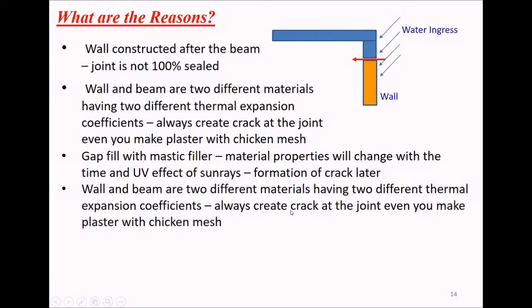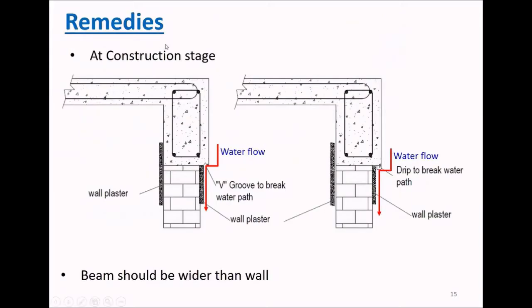So always this crack is there. We have to expect the crack is there, right? So what are the remedies we can do at the construction stage? We can introduce a V groove here at the beam, right?